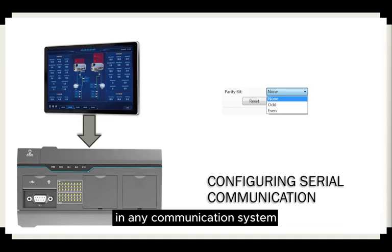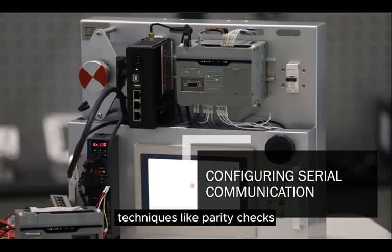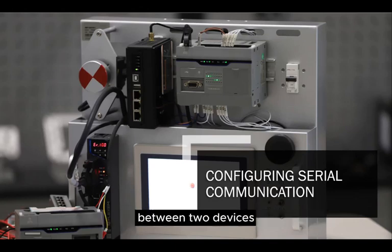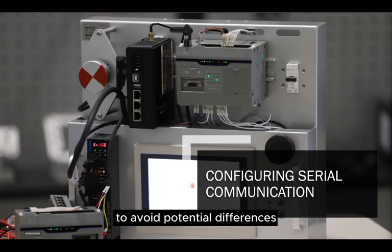In any communication system, errors can occur. For serial communication, error handling is crucial to ensure data integrity. Techniques like parity checks, checksums, and cyclic redundancy checks, CRC, are used to detect errors in the transmitted data. Flow control is used to manage the pace of data transmission between two devices to prevent the receiver from being overwhelmed by data. Proper grounding is essential in serial communication to avoid potential differences that can cause communication errors.